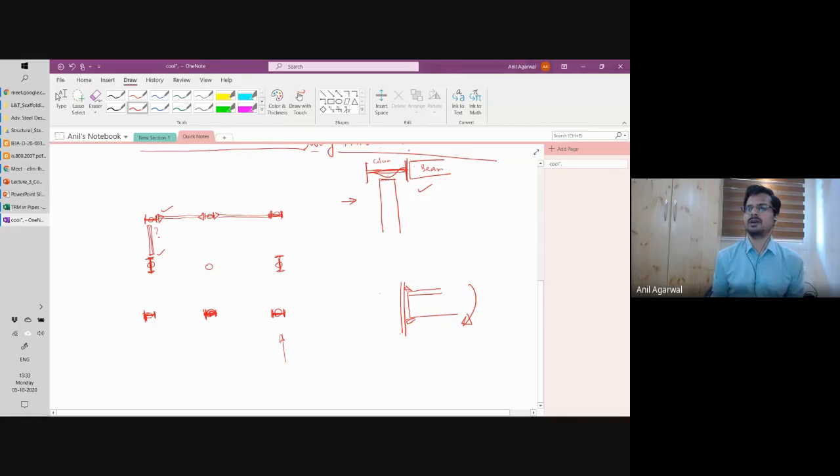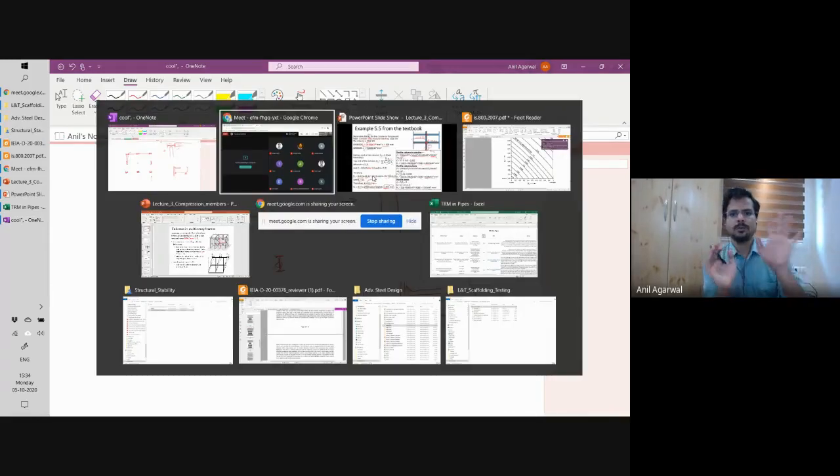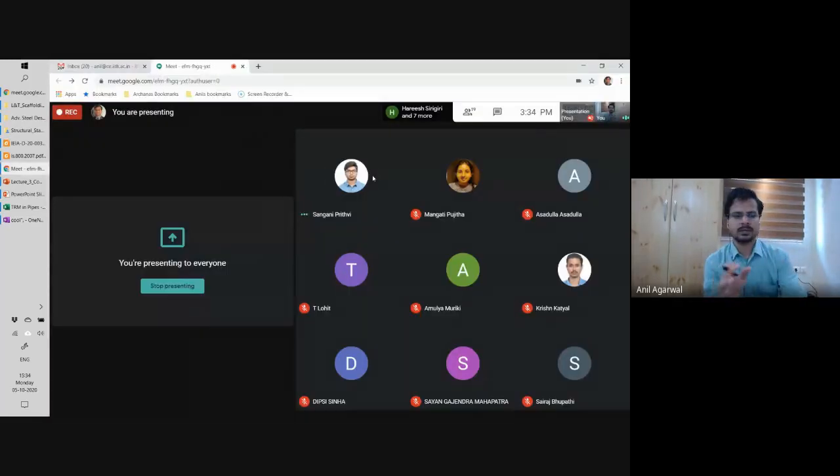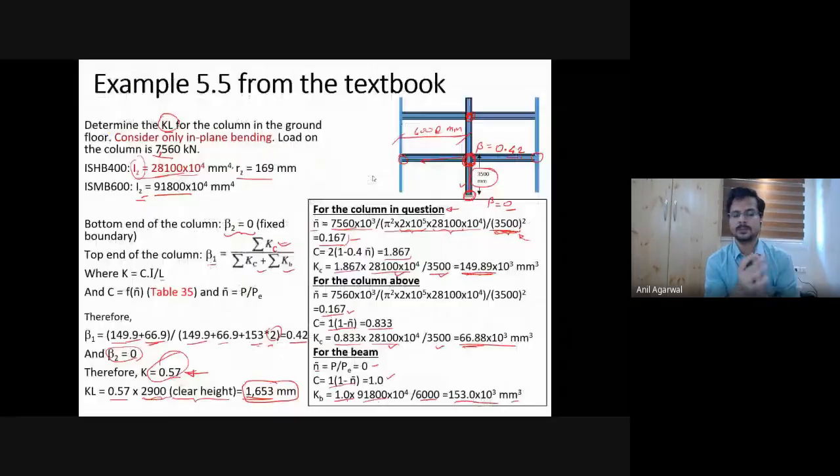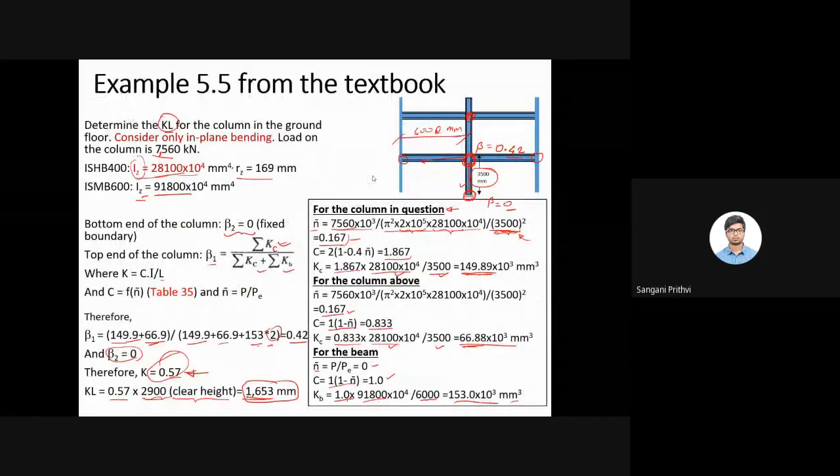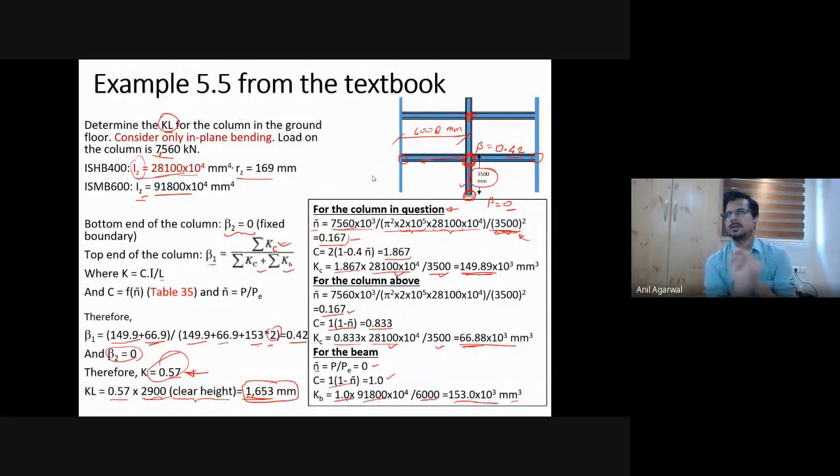So you have to devise a very complicated connection here and effectively make a box of sorts around the column, then connect the beam to that. So this is never done, hardly ever done. So we don't provide a rigid connection in the minor axis of a column. Okay. I hope I didn't take too much of time and I actually was able to explain what you were asking. Yes. Right. So therefore, that question does not arise about minor axis so much, because in the minor axis, mostly the connections will be pin connections.